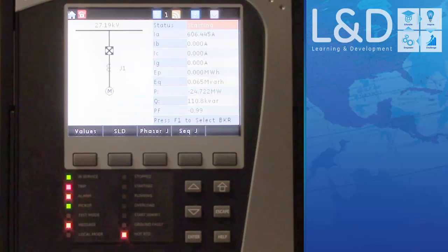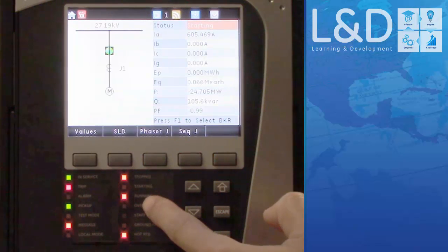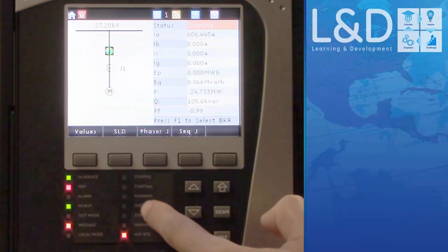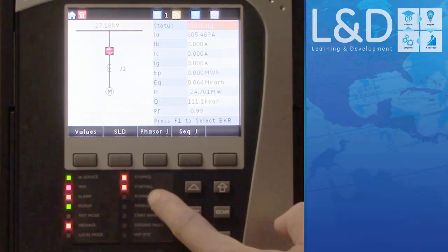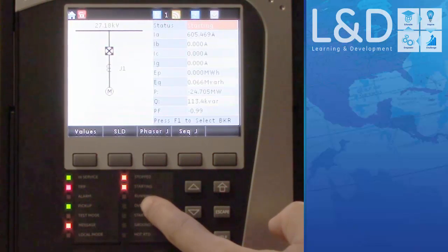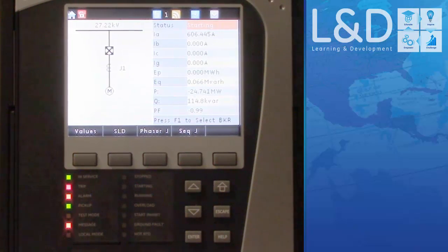After rebooting the relay, we can use the RTT test set to check the status of the relay. So we can turn on the contact input 1. We see LED 8 is turned on and also LED 10. If I turn off 1 and turn on only 2, I see the LED also turned on. If I turn on both, the LED turns off. And if I turn off both, the LED is off. So that proves contact inputs 1 and 2 form an XOR gate.